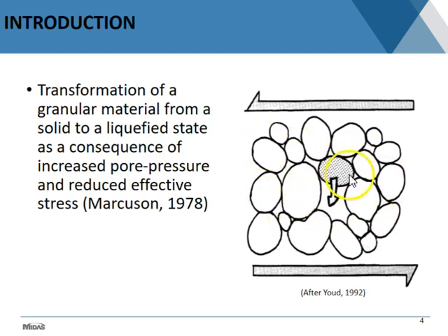Now, in this figure that you see at the right, the idea is that when you have a material that is basically sandy material, maybe some silts or some fine gravels that are in loose condition, you have enough space to reaccommodate the particles once you have a certain amount of shaking.